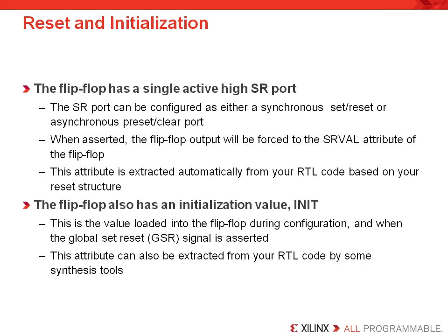The flip-flop also has an initialization value that's also inferred from your HDL code, and that is given the attribute INIT. This is the value loaded into the flip-flop during configuration, and when the global set reset, that's the GSR net signal, is asserted. The GSR travels to all the synchronous elements and resets them as part of the configuration process. This attribute can also be extracted again from your RTL code by some synthesis tools based on your coding style as well.